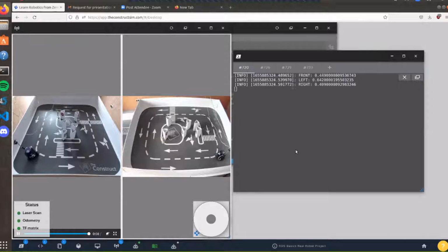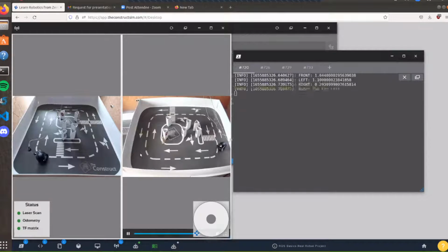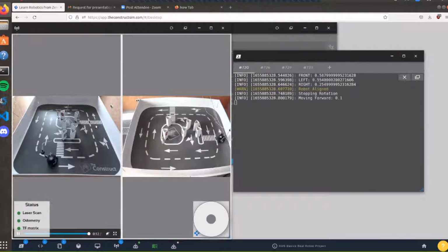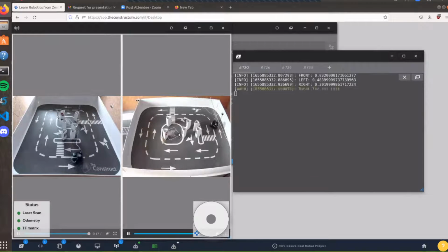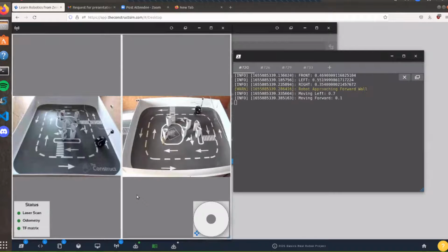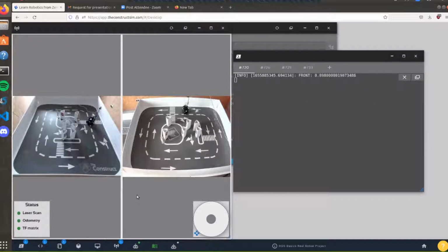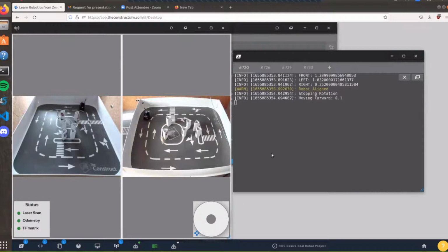Actually, I was having some problems until about 10 minutes ago. It would crash, because when it was approaching the wall, it was too late and then it just crashed. So I raised the detection distance of the front wall to around 55 centimeters, so it stopped doing that. So it turns earlier. Yeah, exactly.